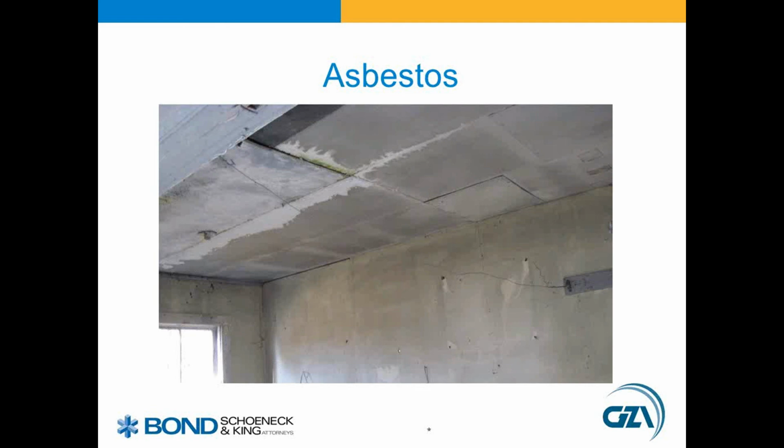First of all, asbestos can be a REC. It is possible that you may go onto the site and find in the back 40 that someone has left a pile of friable asbestos. In that situation, it would find its way into the ASTM report as a recognized environmental condition. But simply having asbestos-containing floor tile or pipe insulation would not necessarily be a REC, but certainly a potential issue with respect to the management of that property.